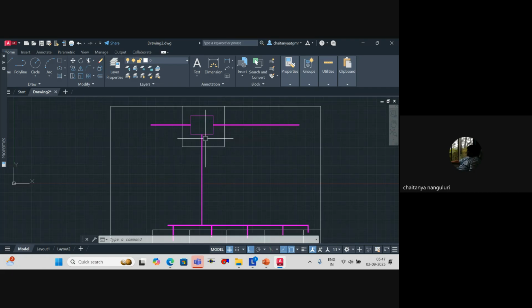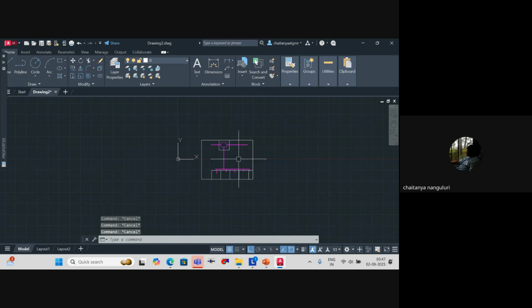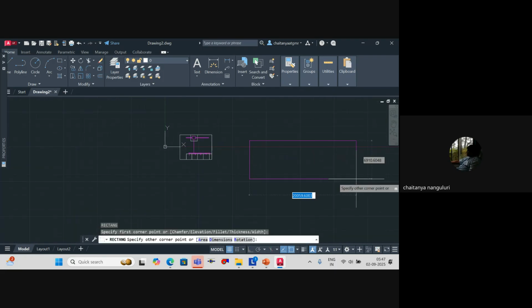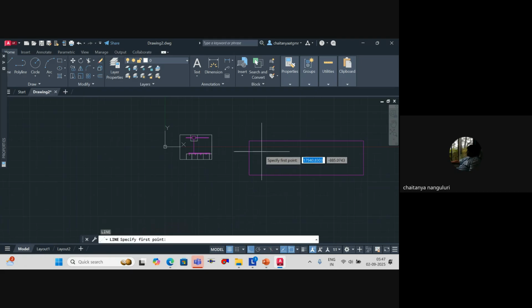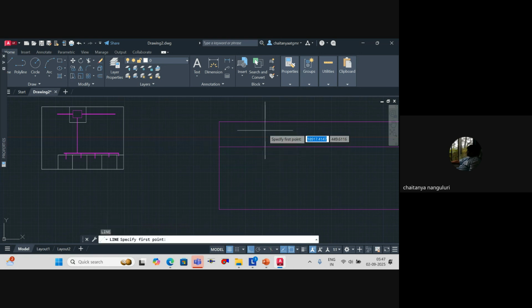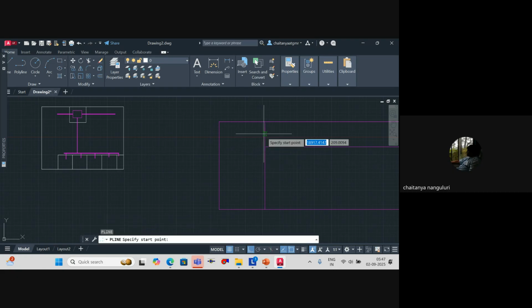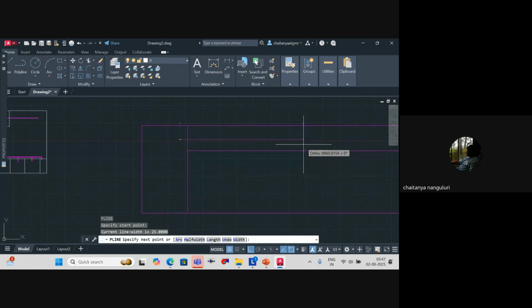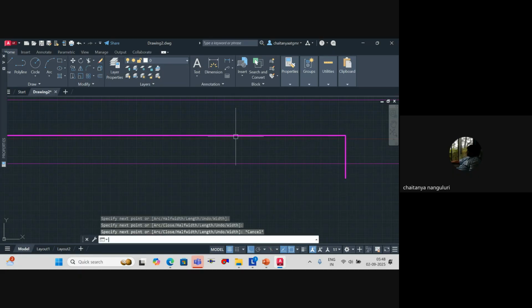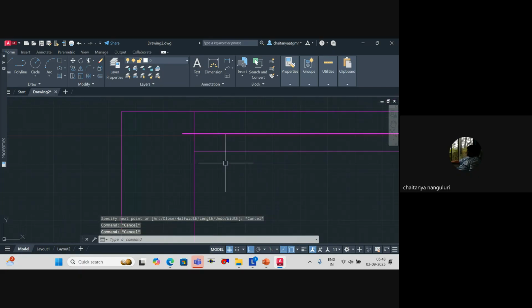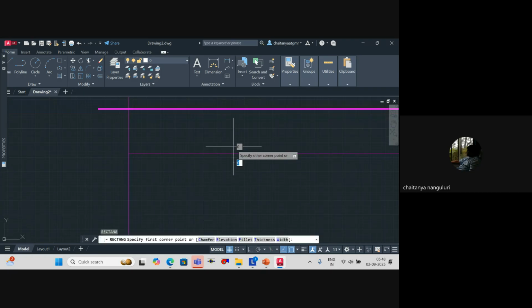When you have this kind of arrangement, what can happen is inside the return air, because obviously this AHU should also have return air, right? So what do we do in general cases? Let's say this is the elevation, I'm drawing it. This is your false ceiling, and in the AHU room you don't have any false ceiling anyway, so your AHU room will be full height. If this is your supply duct to your room space, the return will be through return diffusers, punctures in the ceiling.